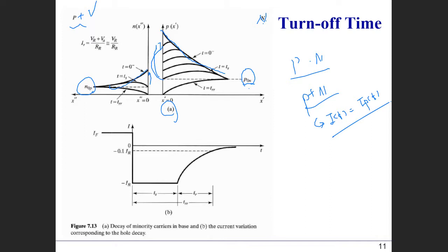And then as a switching device, if we suddenly go to reverse bias, in reverse bias your carrier concentration falls below the equilibrium value. But from forward bias to reverse bias, a certain transition time is required. As a switching device, we typically try to minimize this switching time in the structure. Any other question? Everything is okay?